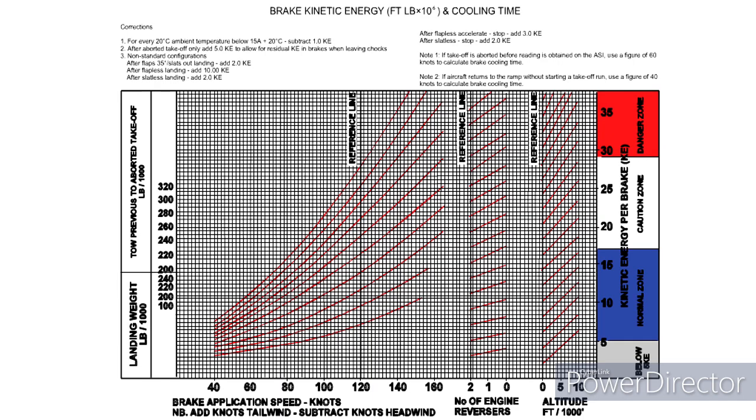During the application of brakes, a considerable amount of energy is absorbed. This energy is released in the form of heat, which must be dissipated. The brake packs, wheel assemblies and tyres are capable of absorbing a certain amount of heat before they fail. Some method of determining the amount of energy absorbed will facilitate decisions regarding precautions and actions to be taken after an aborted takeoff, a landing, or simply taxiing the aircraft around the airfield.